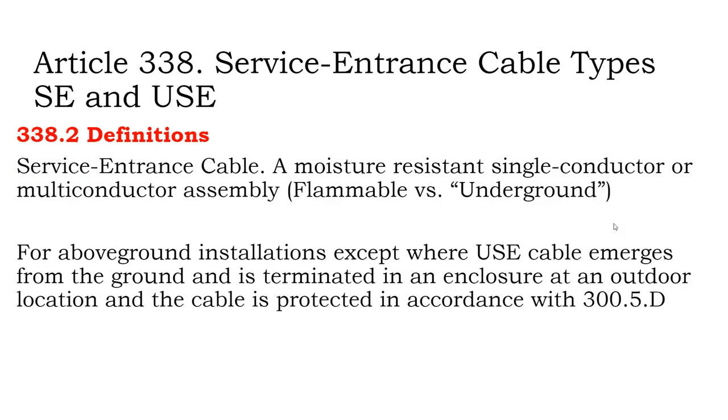Maybe only 10 feet of that will be conduit, and then they'll transition into the earth just to make the pulling and the installation of that underground cable easier. So USE cable is useful for ground mounts, direct burial.